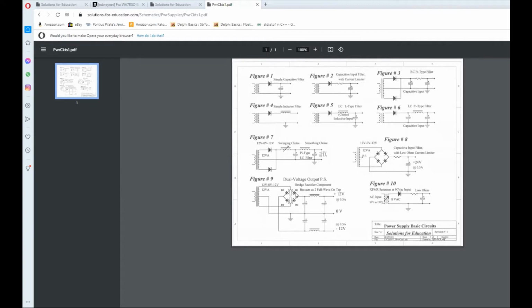Now, here's the same circuit, but done differently. Now we're going to use a bridge rectifier, and we're going to use a center tap. And right away, that reminds us of this guy here, which is a full wave center tap system. And that's what this guy is. Now watch this. See these two diodes, this one right here and this one right here, they look exactly like these two with this common ground here. So these two diodes here work like this circuit here, and these two diodes here work in the same way, but opposite polarity. That's the advantage of this circuit here.